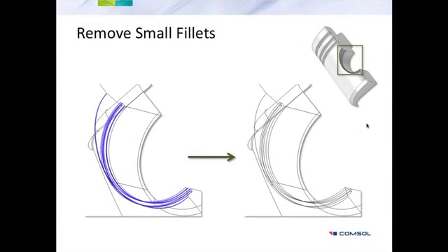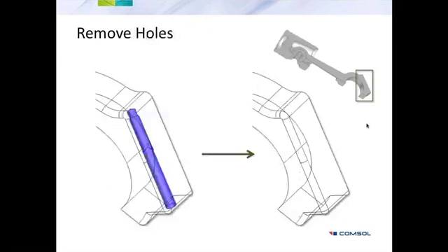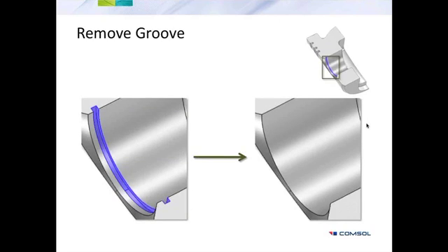Another example here showing how you would remove certain smaller rounds from the geometry. And finally, just to show an example, you can actually freely select larger details as well to take out. So in this case, I've taken out the bolt, but I still want some material there for my heat transfer analysis or the structure analysis, and I just assume that it's part of the conrod, and you just select those faces and remove them and fill it up with material in just one operation.